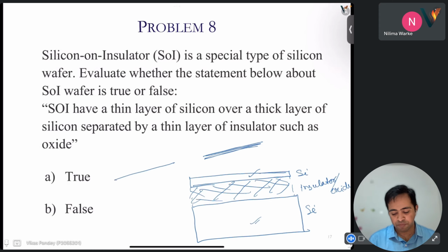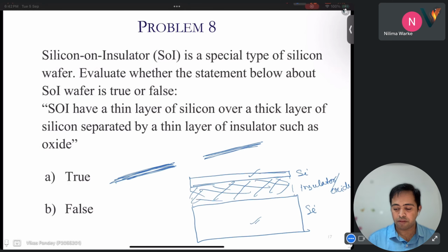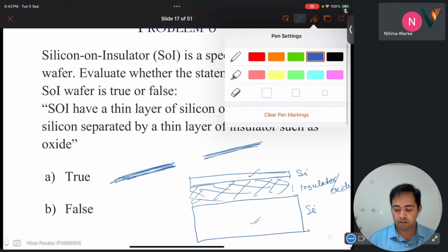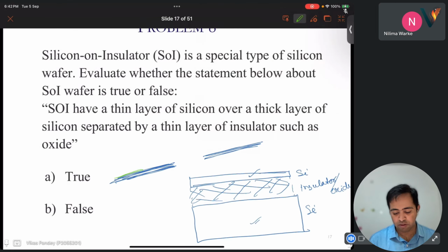two silicon wafers and oxidize them. So a silicon dioxide layer will be here on top and here on the top. Then we bring them together, and using some force, if we keep them together, they will stick. Oxide and oxide parts will stick.